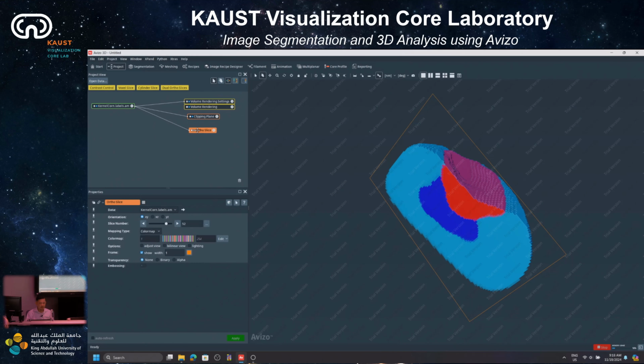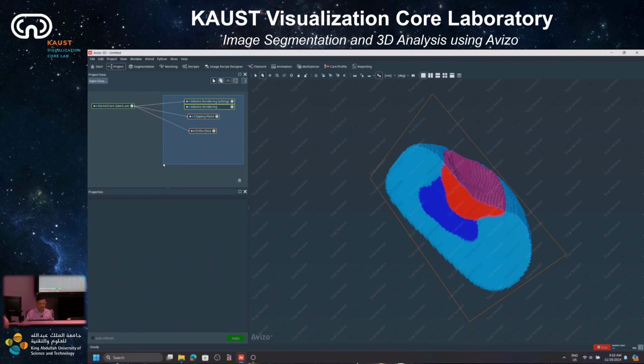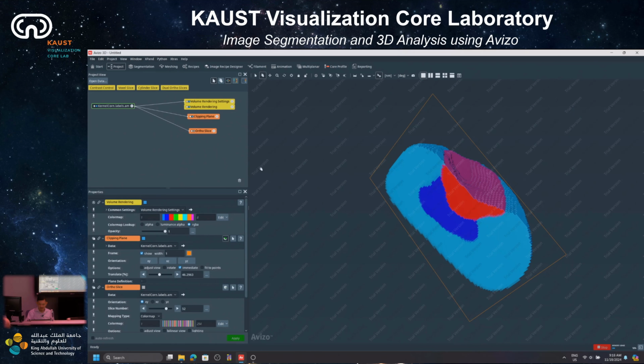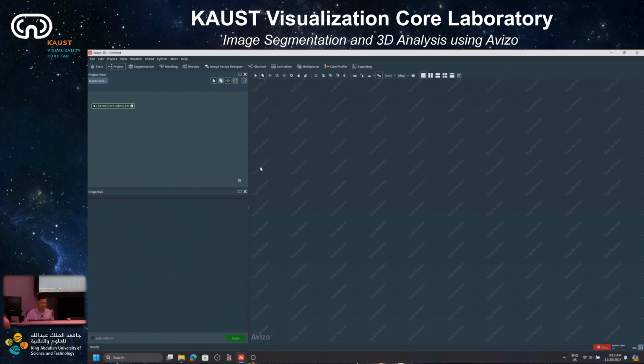So now we're gonna work on the dedicated meshing workroom. So I can just remove everything, so you can see that you can drag around the object you don't need and press the delete button from the keyboard. To start to generate mesh, just select this meshing workroom over here. It's the 4th tab on the top menu.